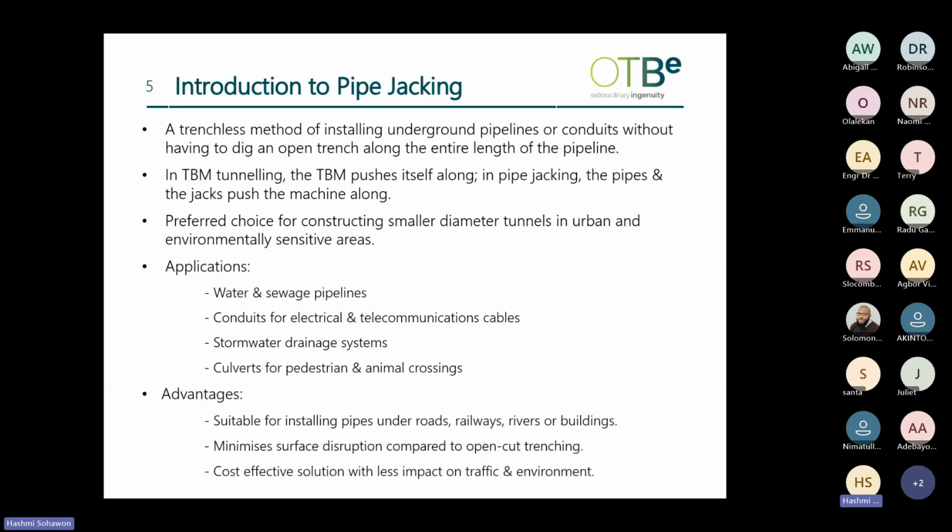To begin with, I will introduce briefly what pipe jacking is so that you can have a better appreciation of the type of tunnels that we are dealing with in this project. Essentially, they are a trenchless method of installing the underground pipelines or conduits without having to dig an open trench along the entire length of the pipeline. In TBM tunneling, the TBM pushes itself along, whereas in pipe jacking, the pipes and the jacks push the machine along.